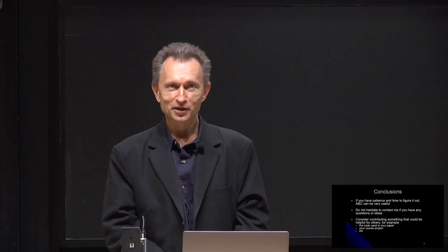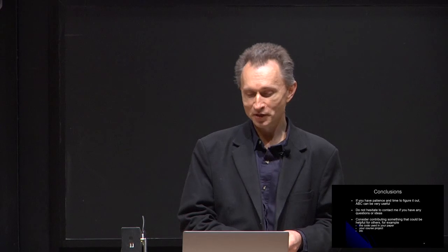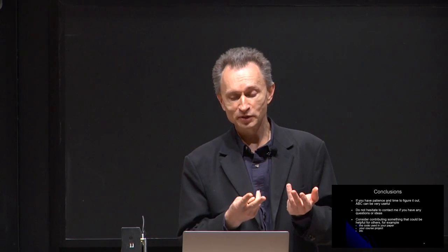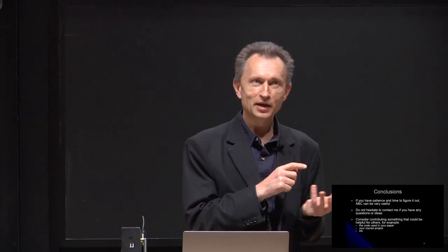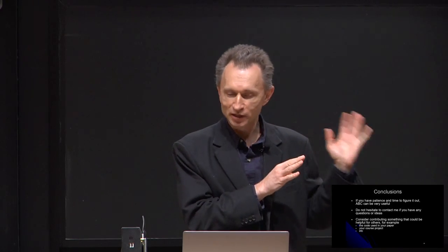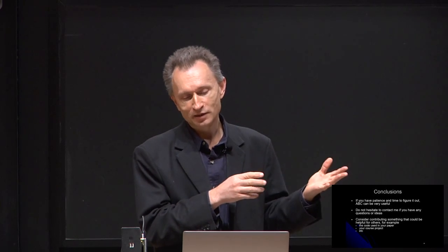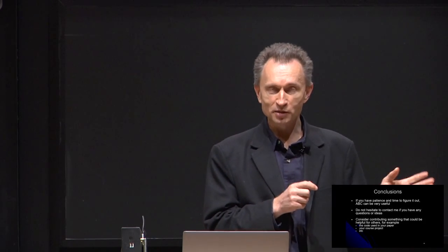I'm very closely collaborating with everyone involved in the Mockturtle team, so I know what they're doing. Indeed, in some ways, they have outperformed ABC. They have a very nice technology mapper which works with multi-output cells, which ABC doesn't have. Recently, they have a new delay optimization package, which again, ABC doesn't have. Then in the past, I collaborated with someone in the Mockturtle team. They developed simulation-guided resubstitution. Again, a very nice feature, and I didn't have time to backport it into ABC. So indeed, some specific transforms are on par or better in Mockturtle.